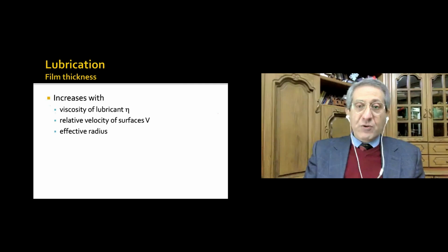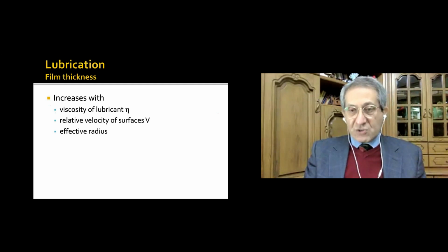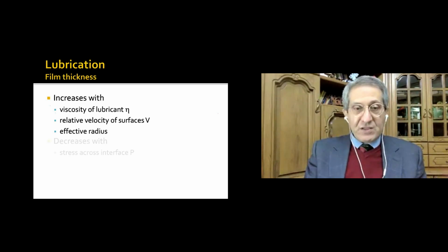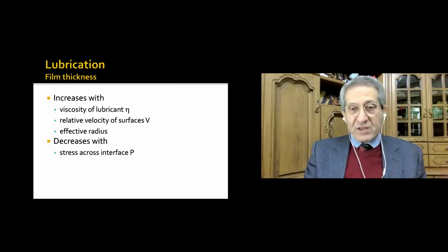The fluid film thickness depends on multiple factors. As in the example of the water ski, it increases with the increase in the viscosity of the lubricant, the relative velocity of the surfaces, and the effective radius. The fluid film thickness decreases with the stress across the interface.